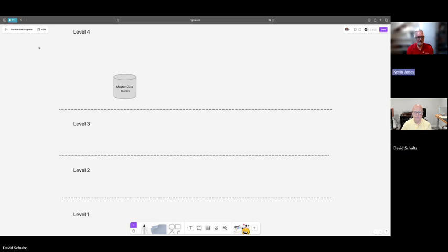Okay, awesome. Perfect. So moving along to familiar territory, this is where we're going to get into the ERP. That's your enterprise resource planning. And I guess I should just clarify real fast, the levels that you see here on the left, those are referencing again the ISA 95 standard, where you have your level 1, that's the control area. Level 2 is SCADA. Level 3 is your manufacturing operations management domain. And then finally, level 4, those are going to be all your enterprise business systems. So I just wanted to point that out and clarify for people that are wondering.